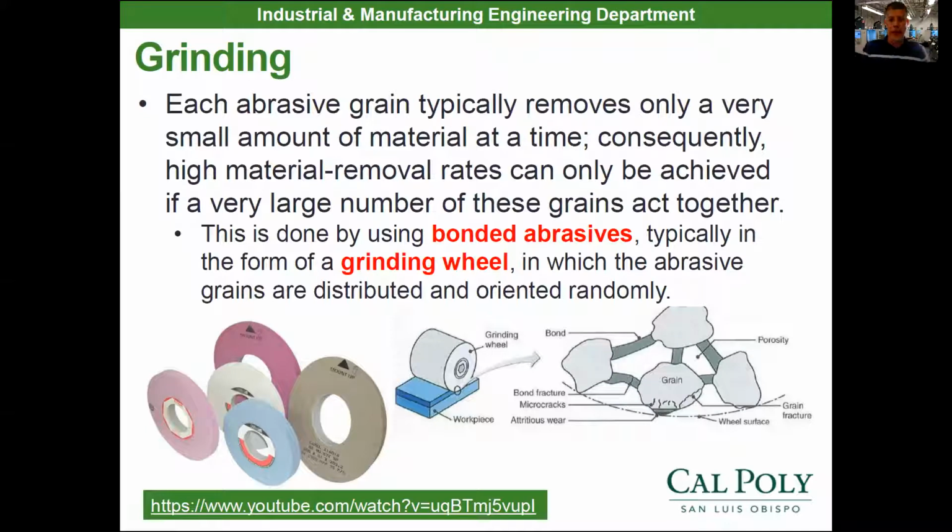So when you get back to in person and you're up at the hangar and you see the different grinding wheels, the one that says do not grind aluminum, do not grind aluminum on that wheel. You could cause a serious out of balance condition and cause damage or even severe injury to somebody. So please don't do that.